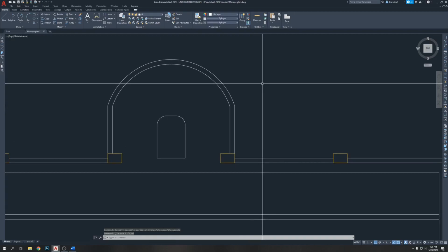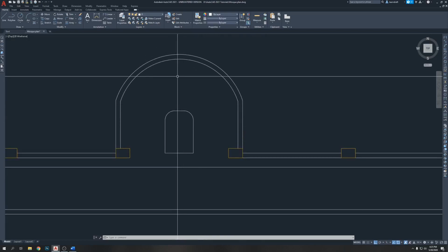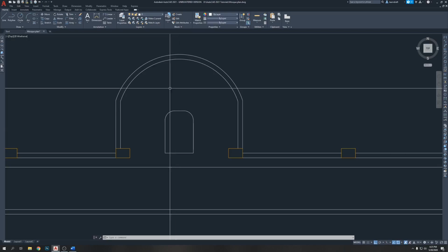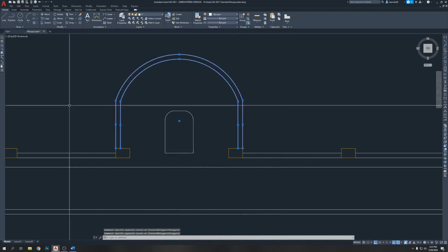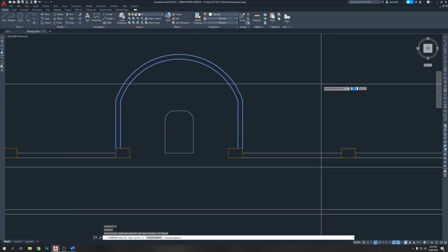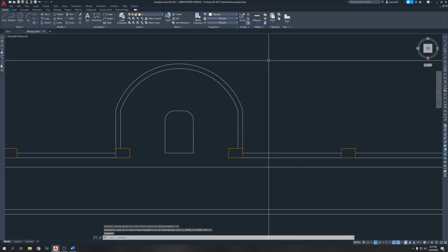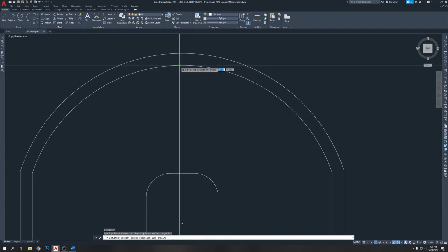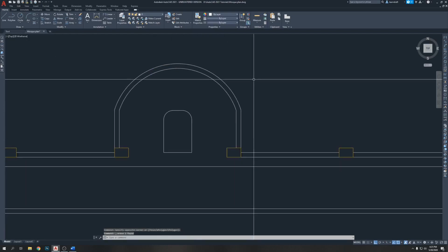and what we'll do now, so Imam is going to stand here. There is too much space in front of him, and there is going to be a place actually for azan. So I think this, if we push this round like 1 feet inside, we can. So select it, S for stretch, enter, push it like 12 inch inside. So the mihrab is now 9 feet actually, outside to outside. DLI, enter, see what is this, like from middle to there. It's like 9 feet 6 inch, which is not bad.